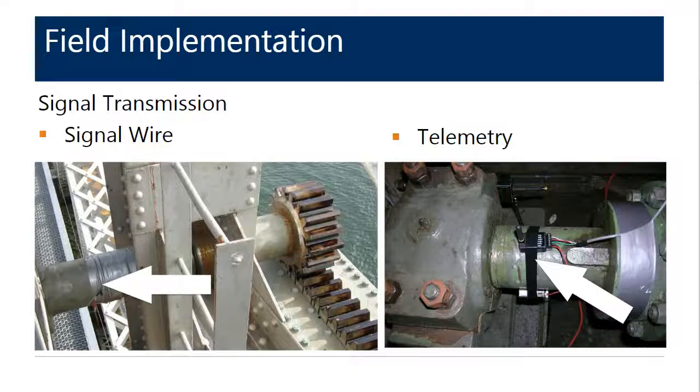The wireless telemetry signal, in our experience, has been a little less reliable than the wire connection. So if your recording is absolutely critical and you can't easily afford additional operations, it may be beneficial to use a wired connection. Now, there is one caveat to that, where the shaft speed, or the shaft that you selected for instrumentation, rotates at a high enough speed that it is dangerous to unwrap and wrap wires during operation. It is highly desirable then to use wireless telemetry to transmit your signal.